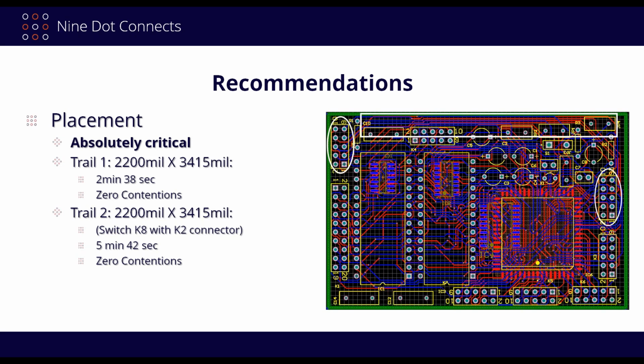What I did over here is I said, okay, I'm just going to route this board based on the size that it is. It took 2 minutes, 38 seconds, no contentions. Then I took the same board, unrouted it, and took K8 and K2. These were the two connectors that we had over here, and I swapped them. They are definitely not in their optimal places. I ran it again, and you can see it took pretty much double the time necessary to complete.